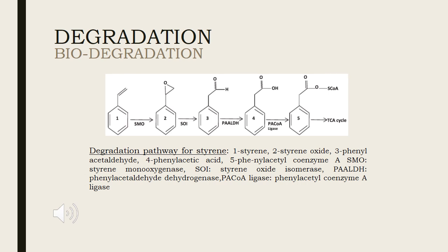Polystyrene is relatively chemically inert. While it is waterproof and resistant to breakdown by many acids and bases, it is easily attacked by many organic solvents. It dissolves quickly when exposed to acetone, chlorinated solvents, and aromatic hydrocarbon solvents. Because of its resilience and inertness, polystyrene combusts incompletely as indicated by a sooty flame.